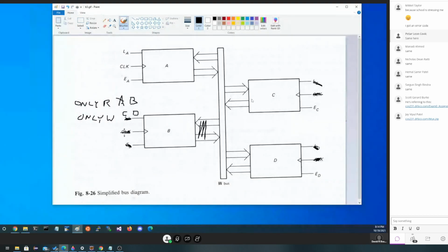So yes, you could. Could we have anything that loads without a clock? Simple two-letter answer to that one. Yeah, that's right. You can't. If we're going to have a load, we need to have a clock to synchronize with, at least on the bus side. And we didn't define any level-triggered clocks on the other side. So we'll find that they won't be that useful. But this turns out to be an extremely useful architecture.